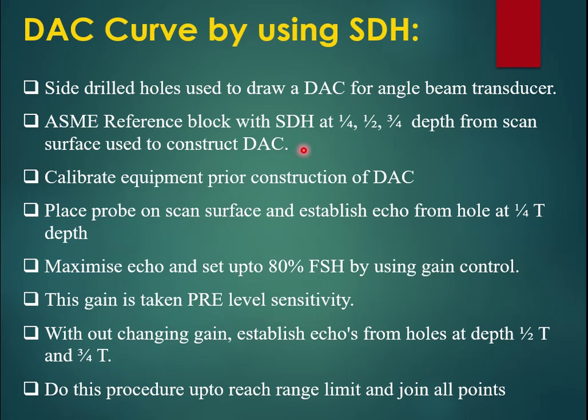The process is similar. The DAC catching, the hole catching process, is similar for both side drilled holes and flat bottom holes. In flat bottom holes, before drawing a DAC curve, we calibrate the equipment. Similarly, before drawing a DAC curve using the side drilled holes, calibrate the equipment for DAC. So calibrate the equipment prior to the construction of DAC.